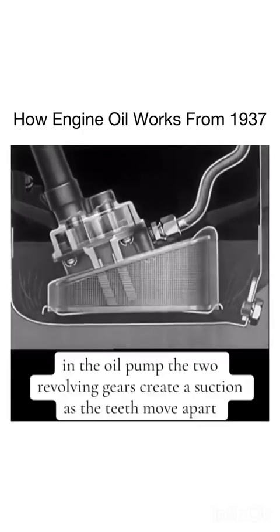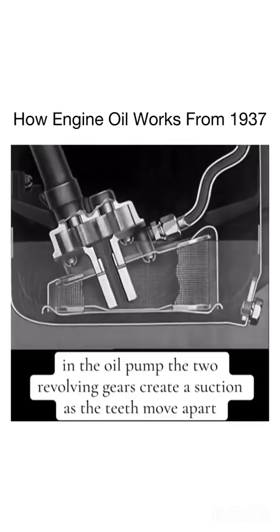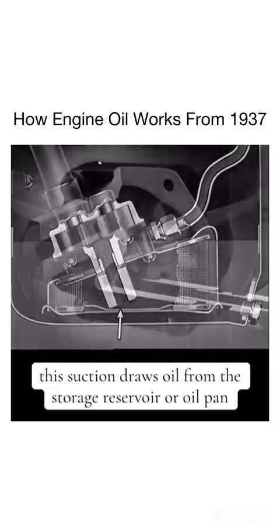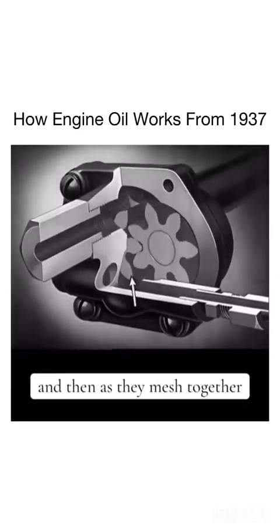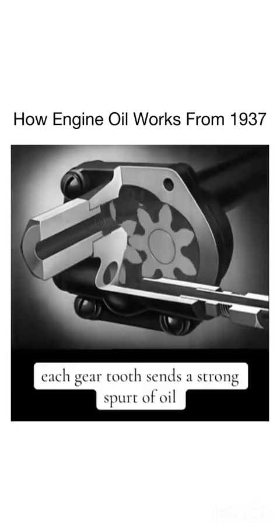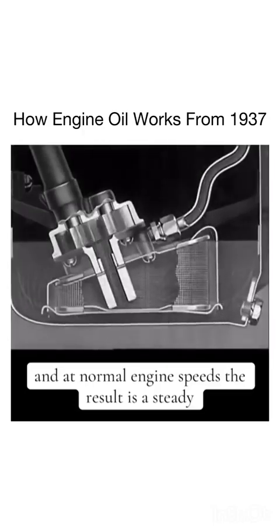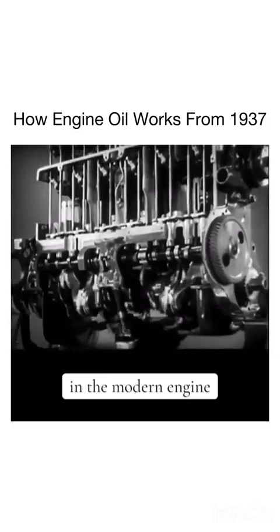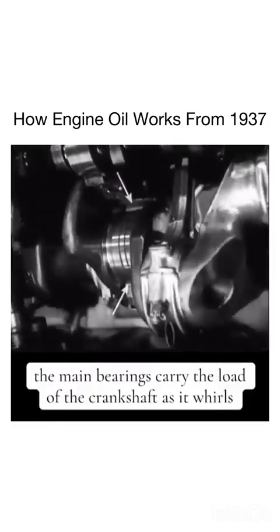In the oil pump, the two revolving gears create a suction as the teeth move apart. This suction draws oil from the storage reservoir or oil pan. The gear teeth carry the oil around as they revolve, and then, as they mesh together, force it to the engine parts. Each gear tooth sends a strong spurt of oil, and at normal engine speeds, the result is a steady, smooth flow.